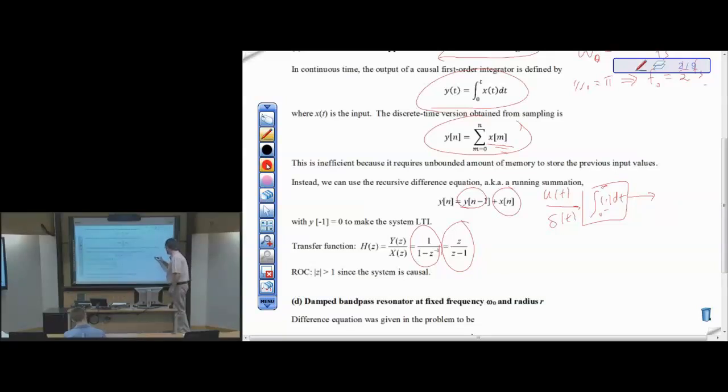All right, so again, the impulse response is the step. If I put another signal in, then it's the convolution of the input and the impulse response. And the impulse response is another step. Right, that's the ramp. Goes without bound.